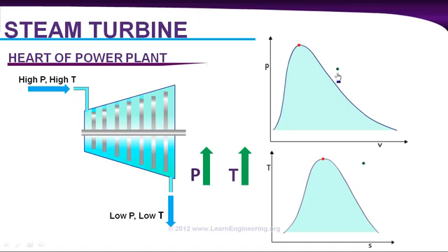And this is our starting point, a high pressure, high temperature steam. During this process, we know pressure decreases, so in a pressure-volume graph, the pressure will come down. Since this is in a gaseous state, obviously the volume will increase with the decrease of pressure. So this will be the curve. It's an adiabatic process. In the temperature-entropy graph, you know temperature is coming down during this process, and there is no heat addition or heat absorption to the fluid, so this is a constant entropy process. So you can draw it like this: temperature is coming down and entropy is constant.